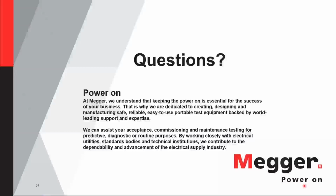Another very common test that people do is the power factor test on the oil at 25 degrees C and 100 degrees C. So each test has its own place. I will not make my decision solely based upon the dielectric breakdown test. That's just one of the tests that I need to do. Just to reiterate, DGA, power factor test, dielectric breakdown, ppm levels, those are very common tests that I would perform on the oil.